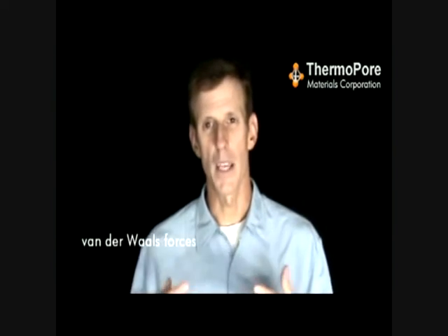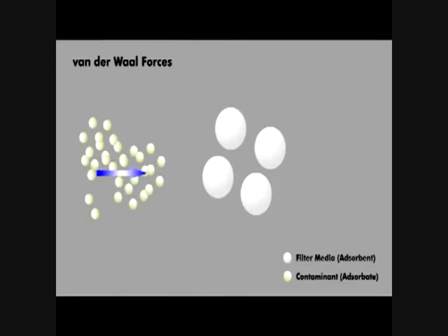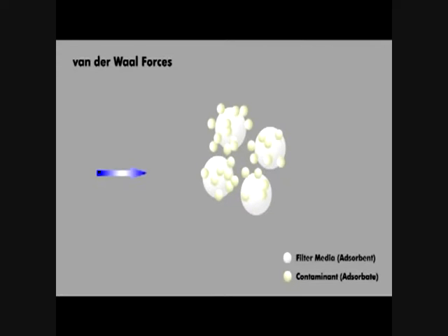Van der Waals forces are relatively weak attractive forces. Nonetheless, they do enable an adsorbent, the filter, to retain particles and actually build up layers of particles onto its surface. Van der Waals forces are more common than you might expect. They're the forces that keep dirt particles stuck to the fibers of your clothes, and they're also the forces that keep cigarette smoke particles stuck to your hair or your skin. Fortunately, these attractive forces are reversible, and adsorbates can be removed from the adsorbent. Physisorption is the mechanism responsible for the capture of solvents and dispersed oil particles and hydrocarbons and silicones. Okay, so that's physisorption in a nutshell.